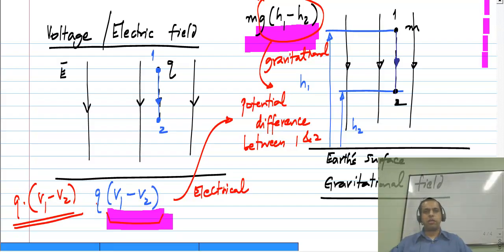So what is the bottom line here? Instead of dealing with charges and electric fields, we deal with currents and voltages. You can see that these are some sort of aggregated quantities. Current is basically the total amount of charge that is flowing through the wire or across the surface in general, but we'll consider them through wires and elements. And similarly, the mathematical definition of voltage is the integral of the electric field. So basically, a voltage difference between 2 points represents the energy gained by a unit charge by going from the first point to the second point. So we'll deal with these things instead.